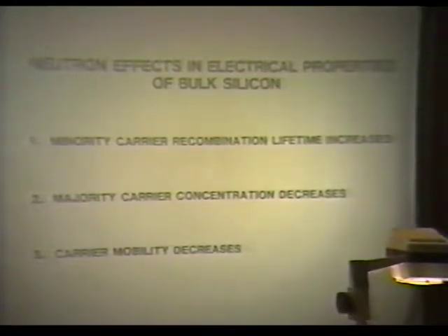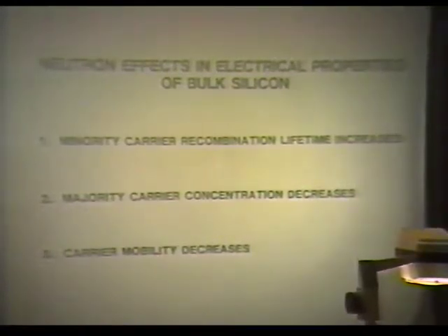And these defects act sort of like lots of holes in a putt-putt game. You know, you're putting your golf ball across the green. Al understands this, he's a golfer. And you want it to go in one cup. You want it to get collected over there, the other side of the base collector junction. But the defects act just like lots of cups out there in the base region. And so lots of the carriers that you're trying to transport across there fall into those holes you've created, into those defects. They act like traps.